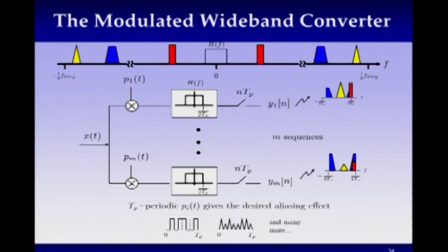So I told you it does, but now let me convince you. We know from basic Fourier series that if we multiply our signal with a periodic function, then in the frequency domain, we're convolving the signal. And a signal, like we've seen already, that's periodic in the frequency domain looks like a sum of delta functions. Now, if you convolve a signal with a delta train, what are you doing? You're aliasing. That's the definition of aliasing, right?